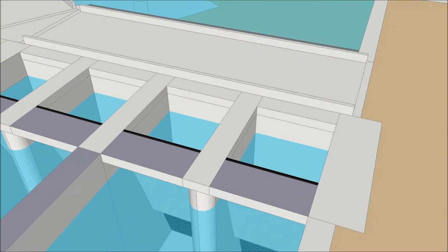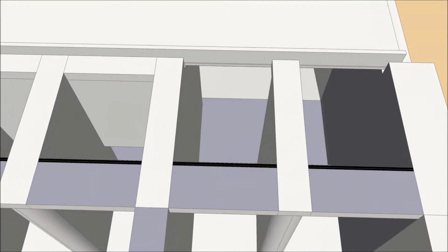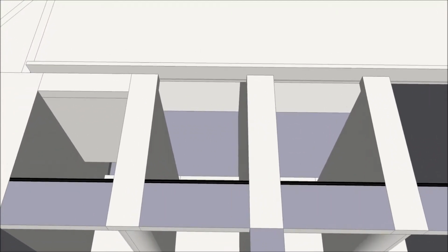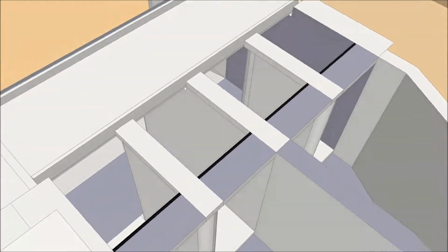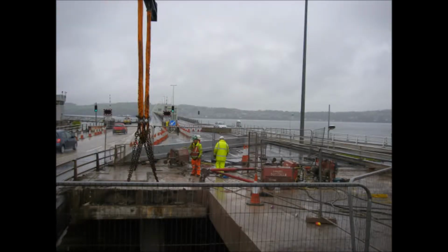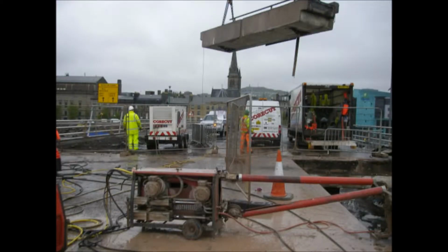sections. The demolition methodology will use diamond wire cutting technology, and the decking and debris wall will be removed in slices, similar to what's illustrated in these pictures. This technology provides very precise cuts, which minimizes damage to the remaining structure.